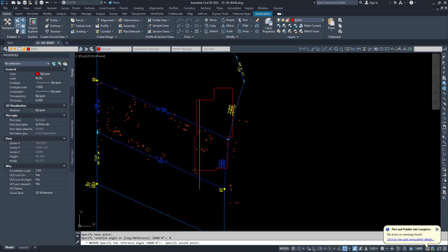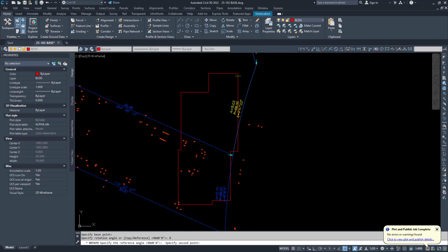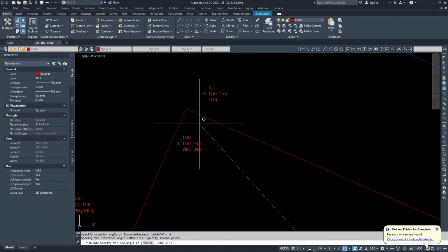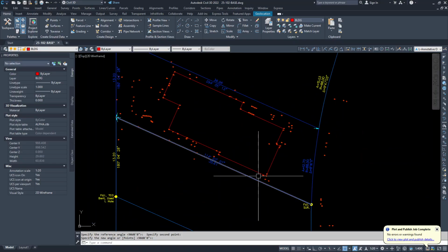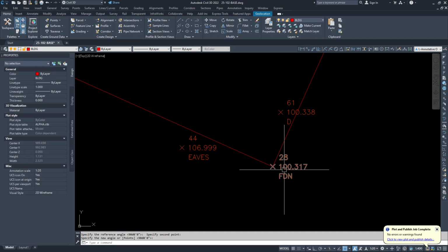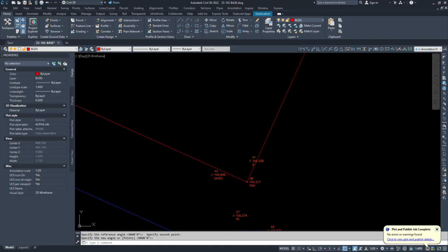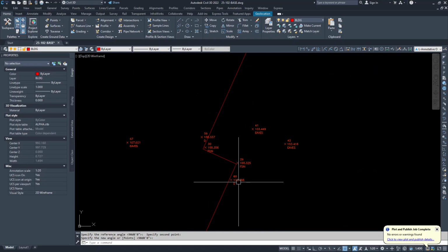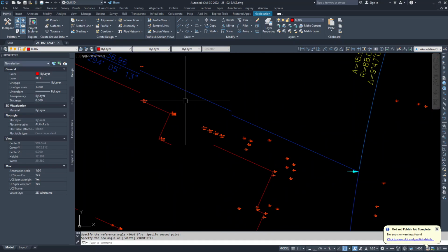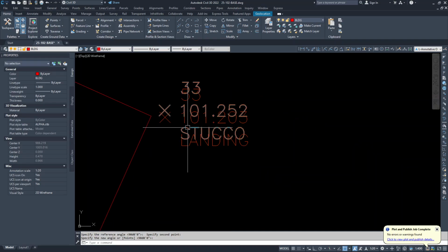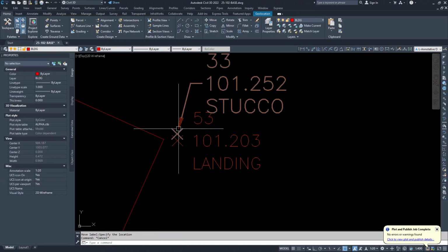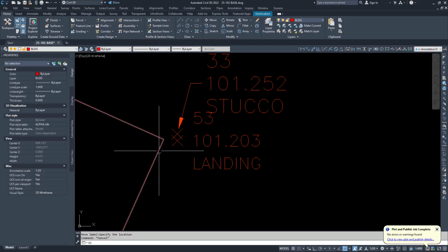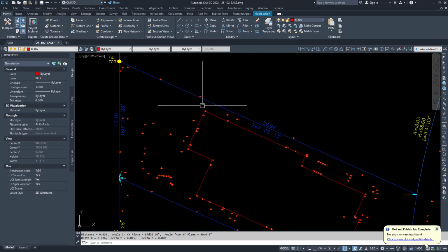so that I don't know, let's just pick this. I hope he has a measurement over here. And he does. That's foundation right there. Okay. So he has actual surveyed points, some are at foundation corner, some are at, let's see here, for example, stucco corner. He probably couldn't see the foundation corner here. So he shot stucco. So what's the distance right there? DI for distance from there to there is about 39 millimeters, just shy of 4 centimeters.